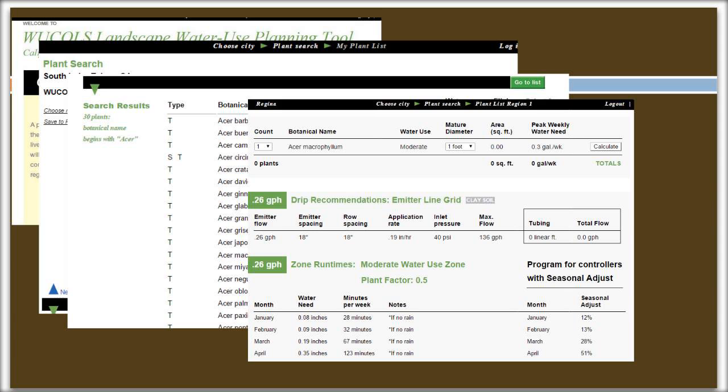You'd want to go ahead and use more water and give more water to a plant that's in full sun in a hotter climate on perhaps the apex of a hill that's going to be windier and have more evaporative stress. So again, make sure you're not just looking at a computer at the ET values, but that you're looking at where you're placing the actual plant and making some fine adjustments for that plant.